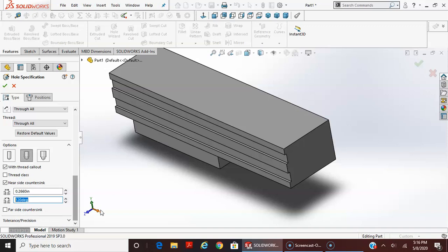Let's say you want a 100 thousandths diameter countersink. From the tip of that 90-degree spot drill, you would go down 50 thousandths, and that would give you a 100 thousandths diameter countersink. Okay, so it's a little bit easier to calculate. You don't have to worry about that too much, because on this one it actually calculates it and shows you the diameter here already. So they actually do both.